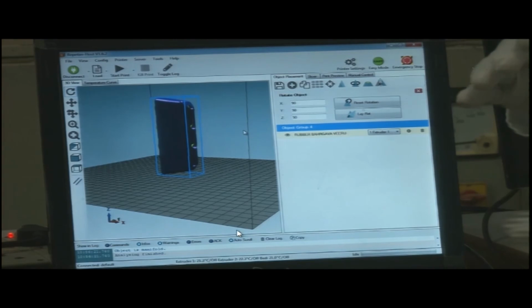What is the drawback when we increase height? Because it is manufacturing layer by layer, this is very important to note. If we increase the height, the total time would increase. So the height has to be optimized, it has to be minimum. These many layers are to be deposited, so the total time would increase.